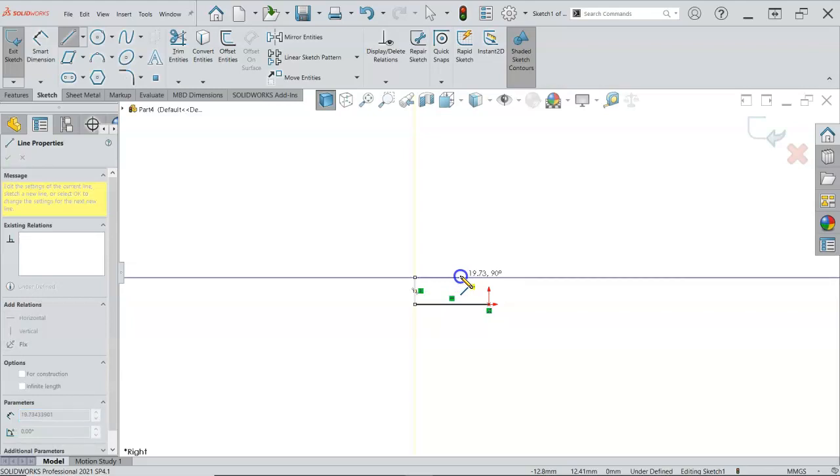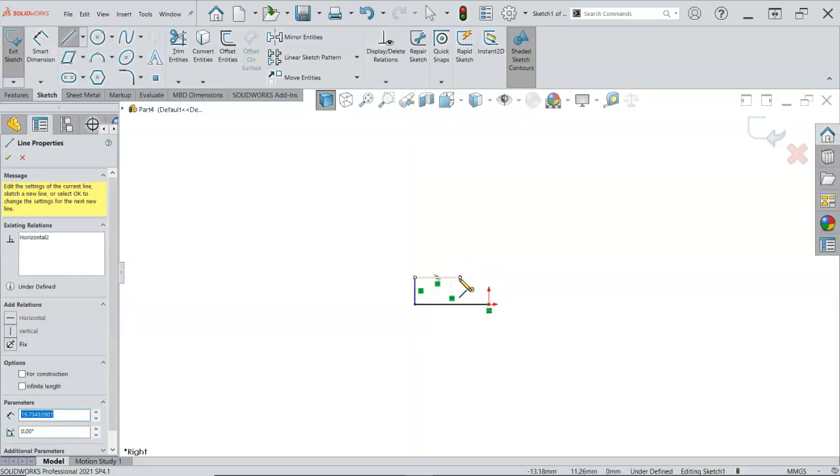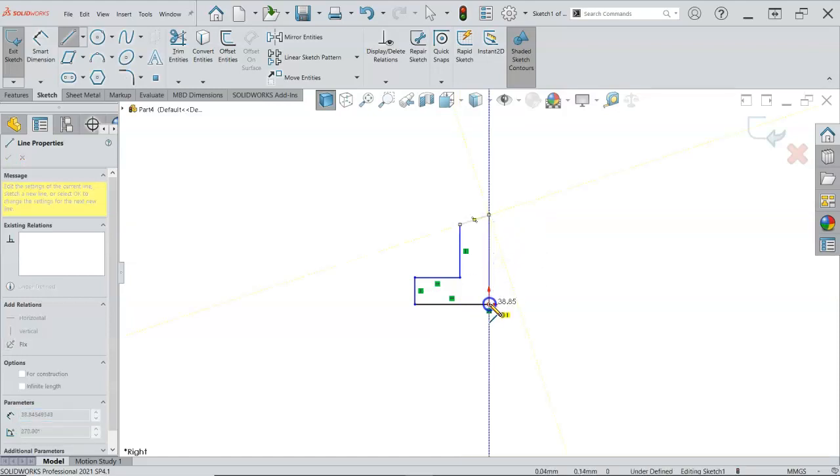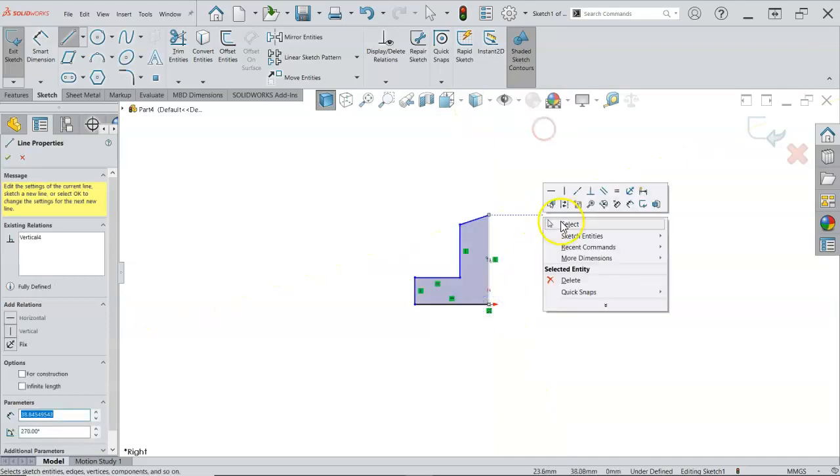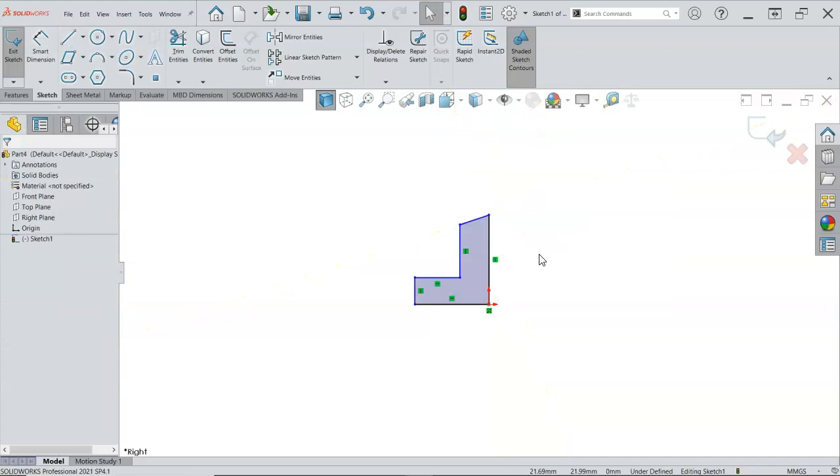All right, so same thing, I'm dragging it out, and then left click on the endpoint, hold down, drag up, watching for that little yellow box. And worst case that happens, I miss. I see my inference line, but I don't get the little yellow box telling me that it's horizontal. No big deal, we will get to that. All right, and then dragging it back to the endpoint, and then I like to right click and select. I could hit escape. There are other methods to work from.